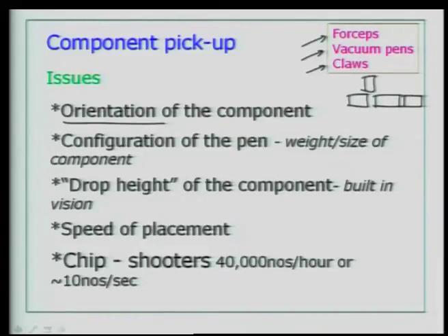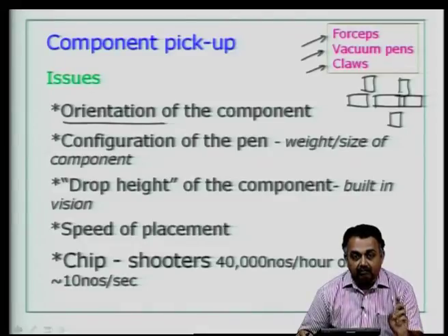So, if you are going to have different orientations along the board X and Y, then you are going to have wastage of time, because the forceps or the vacuum pens have to rotate and then place the component, which will take up time, and this is not a very good design from the viewpoint of the wave soldering process or even the reflow soldering process, because if you are going to have tiny components placed in different orientation close to a component which has got a good height, then you will have thermal issues in the sense that the tiny component or the short component will not attain that much of heat, and therefore, you can end up with a dry joint or a poor joint. So, orientation has to be taken care of by the designer.